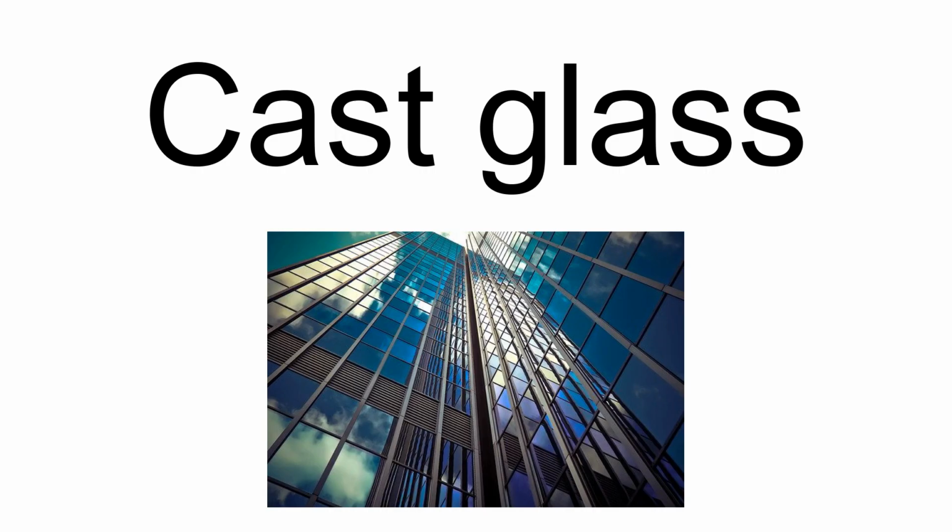Glass casting is the process in which glass objects are cast by directing molten glass into a mold where it solidifies. The technique has been used since the Egyptian period. Modern cast glass is formed by a variety of processes such as kiln casting, or casting into sand, graphite, or metal molds. Cast glass windows, albeit with poor optical qualities, began to appear in the most important buildings in Rome and the most luxurious villas of Herculaneum and Pompeii.